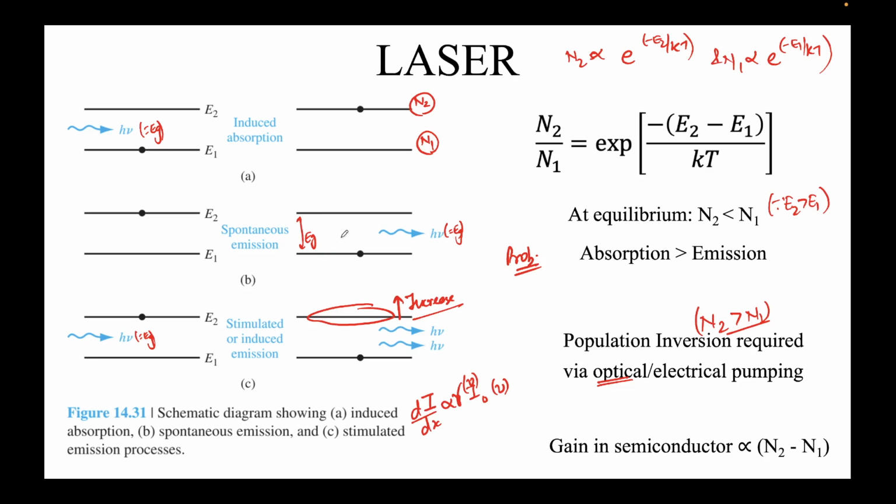Because again, please remember that frequencies which are lower than Eg will not even exist, because the band gap has to at least be Eg. The photon h nu will be Eg, and it's very close to Eg. It's not wide, as we saw the FWHM, full width at half maximum. Remember that 1.8 kT we saw, delta Eg of 1.8 kT we saw for LEDs. It will not be that wide, right, but it can have some width.